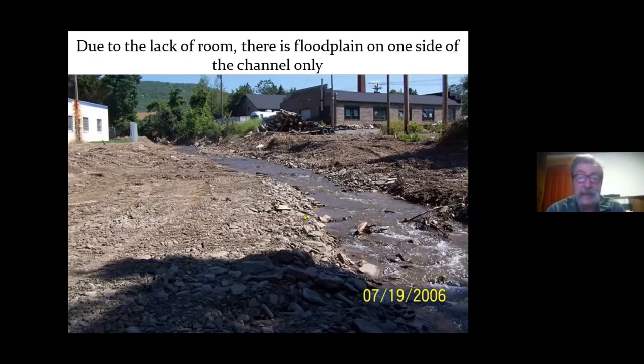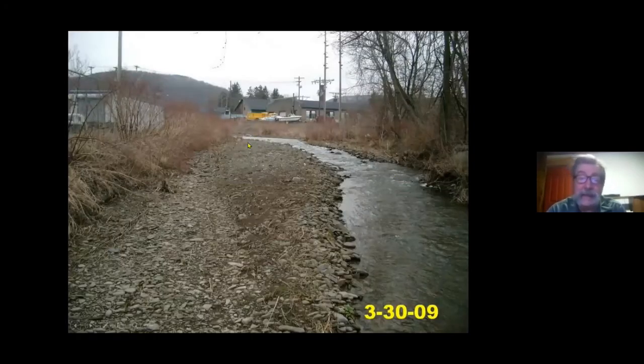And here's an example. Here's that site. They were only able to get floodplain on this one side, but when you take a look at what's there, it's starting to look fairly stable. Vegetation's coming in. That channel is right about where you put it to begin with. It's done some redistribution of some of that material. Like I said, once you get close to that cross section and configuration that you want, nature's going to take over and do some adjustment.